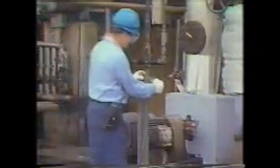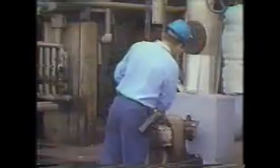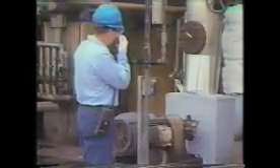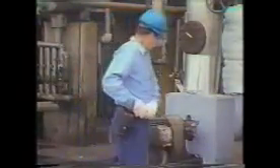Next, he starts the pump he's chosen for a moment and then stops it. This is to make sure that the pump is supplied with electric power and will start when needed. He follows this procedure each time he selects a pump during the pre-startup checks.